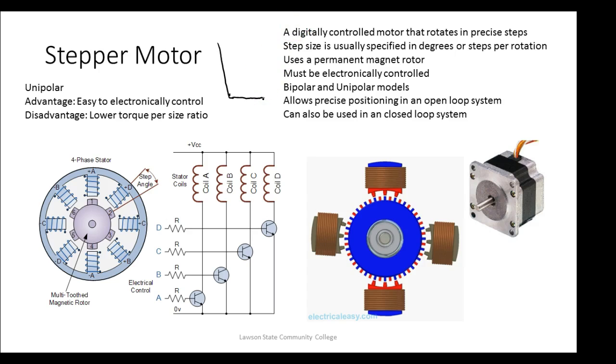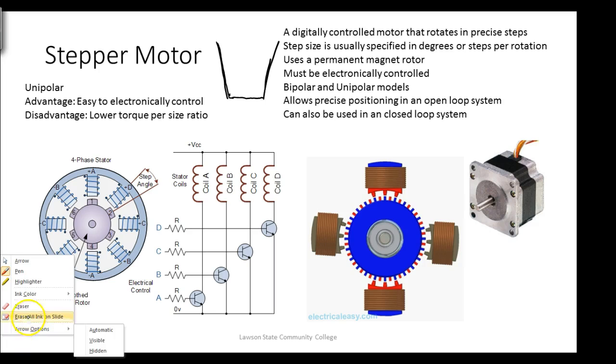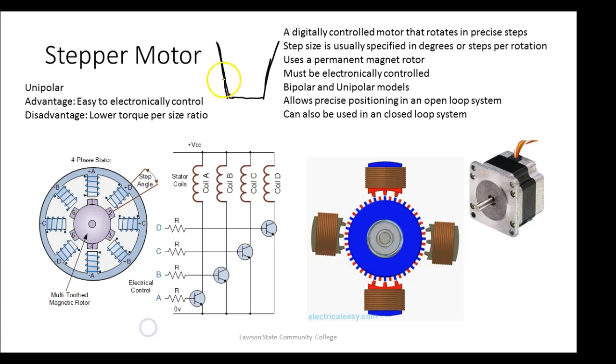And the problem is that we can't cut it off and on instantly. So with our current curve for the motor, we'll do this in a different color. Our current would be doing this. The current is going to be wide open when the transistor's dropping no voltage, and then it's going to go to 0 when it cuts off.